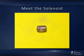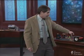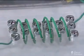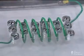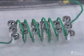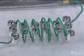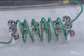Here you actually see a solenoid with iron filings around it, and I'm going to do the same thing with a demonstration over here in which I've got a very loosely wound solenoid, these green wires, and I've got a lot of little compasses under them, and the compasses are pointing sort of northish. Again, in the laboratory with all the metal around, it's hard to get them exactly right, but they're all pointing in some direction, and I'm going to turn on a pretty hefty current, about 7 or 8 amps, and watch what happens to those magnets.